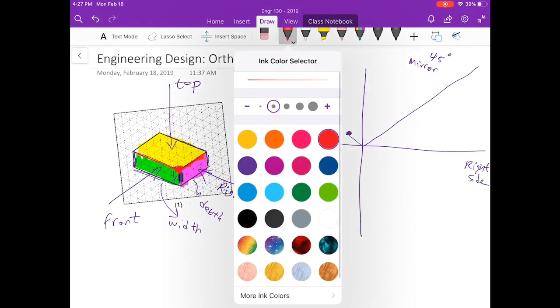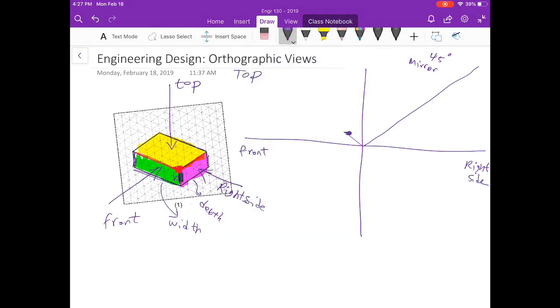So in order to draw the top view, I would be able to see 6 units down here, and then 4 units up here. So this is the yellow highlighted area that you can see from the top. Now I want to translate all these dimensions into the other views, because I know, for instance, the 6 units in the area down here, this 6 units actually is common between top and front.